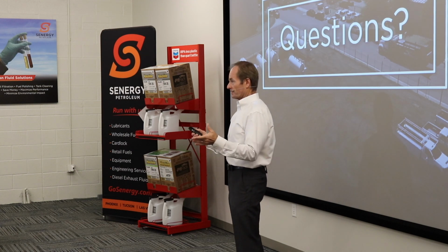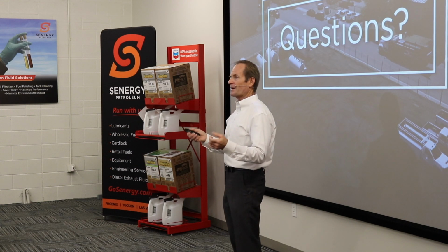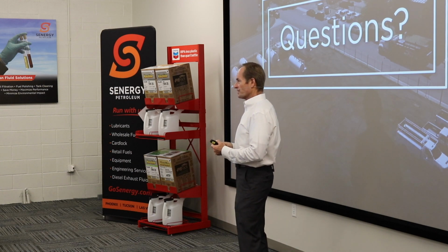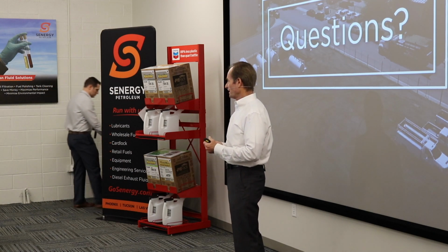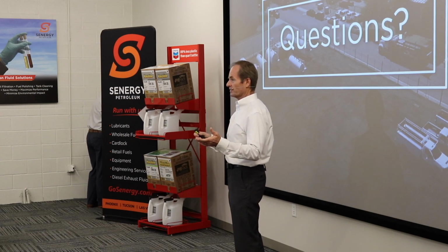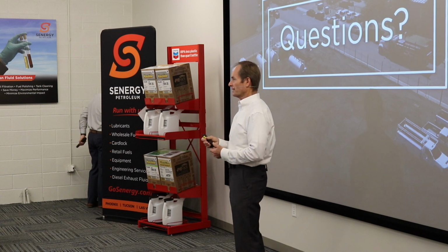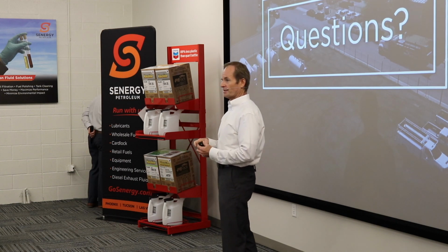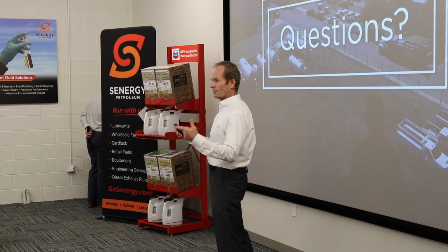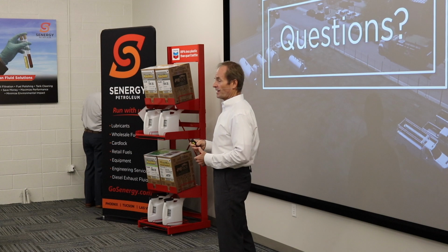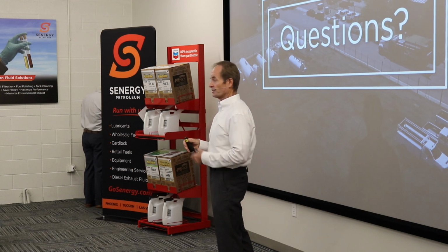So they had to formulate and sell a different power steering fluid with better anti-wear characteristics in it. But recently, with the improvement in ATFs, I've seen requirements now or statements and positions where you can now use like Dexron 6 as a power steering fluid. Still go by what the manual says, but the quality on some of these later generation ATFs is such that it would provide that kind of protection that the old power steering fluids used to.